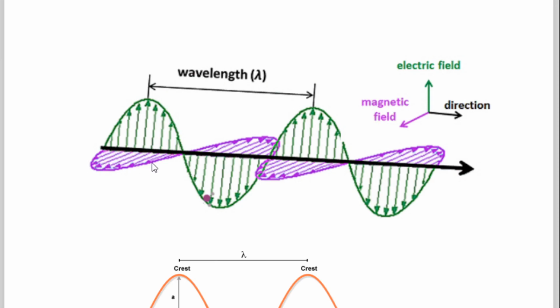Here the violet signal is horizontal, and that is nothing but the magnetic field. So electric field and magnetic field are perpendicular to each other, and here we are interested in the wavelength. What is the wavelength? Wavelength is the distance between two adjacent positive peaks of the electric field, and this wavelength is there. Now we have just discussed that for efficient or effective transmission, the size of the antenna must be equal to the wavelength of that information signal or electromagnetic waves. So this is the wavelength.